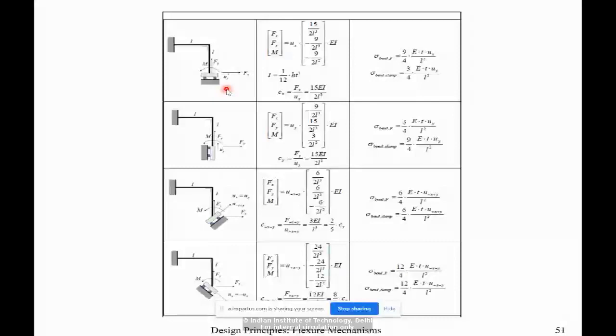Can you put phi equal to 0 here? There are two rollers. It's not pivoted. If it's pivoted, then you can say only uy equal to 0. But it can move in x direction. Y direction, I agree, it doesn't move. But about phi, whether it can rotate.